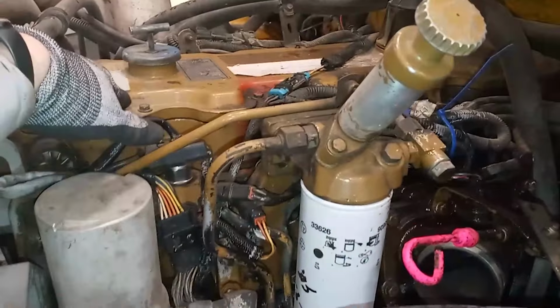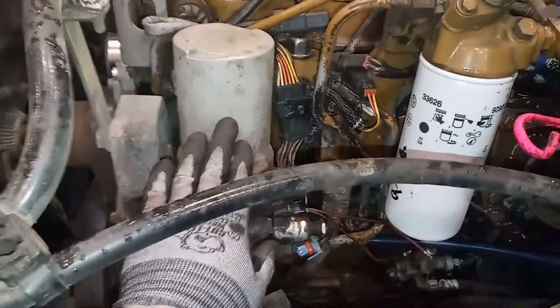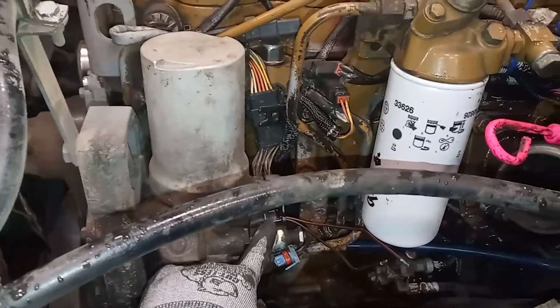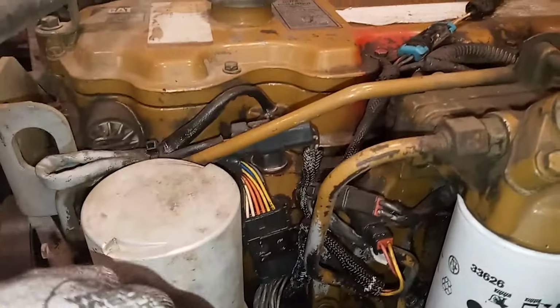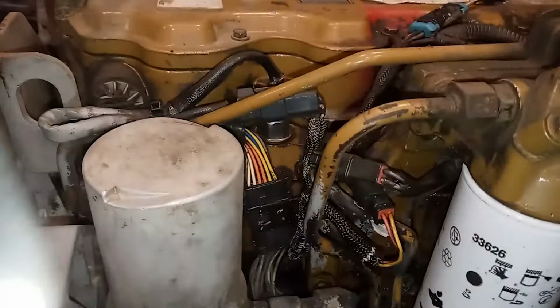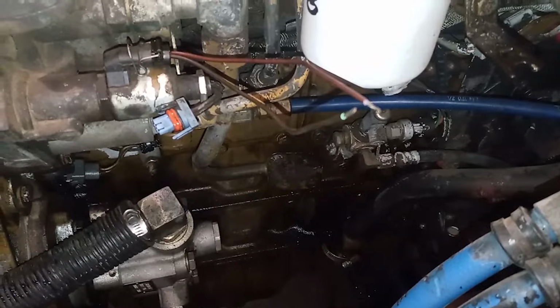So on a 3126 HEUI problem, there are generally three different causes it could be. We could have injector seals leaking, we could have a bad HEUI pump, or the HEUI pump driver itself. On the 3126s with the round top HEUI pumps, those are external and they can be changed, not on the square tops though. It does have a HEUI pressure sensor. It's very, very rare for the sensor to be the cause of the problem though.